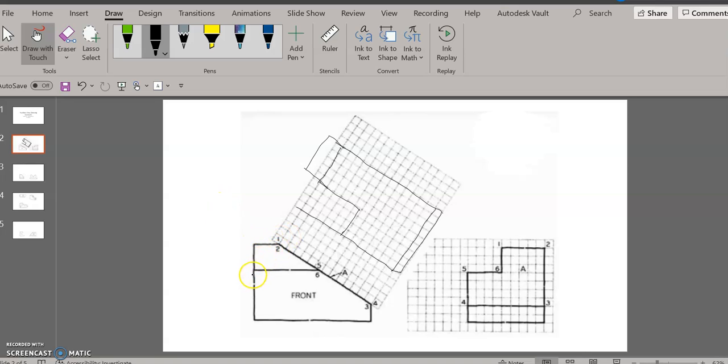Now I need to also project this line. If I take a look at this, that's going to be halfway between those first two lines. So I'm going to draw that back there as well. And that'll complete this surface and that surface. In addition, I'm going to have to also project this back corner. If I project it up, it's going to be about even there. Now that's going to go all the way across, and it's going to be a hidden line. So I can draw that in like so. And I'll be finished with this particular example.